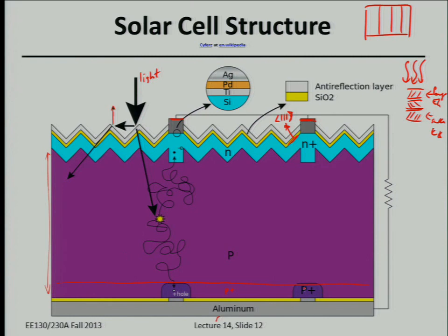Okay, so the question is, are the heavily doped regions more opaque? They have a smaller band gap due to band gap narrowing, so due to that, I suppose you could say it's more opaque, but it's not going to be significant. But certainly, a smooth metallic backside here could help to reflect the light back into the semiconductor region. But I'll verify that. Good. Yes, question?